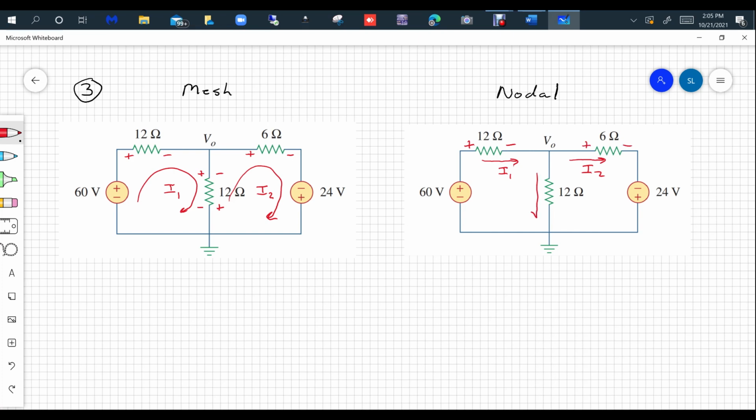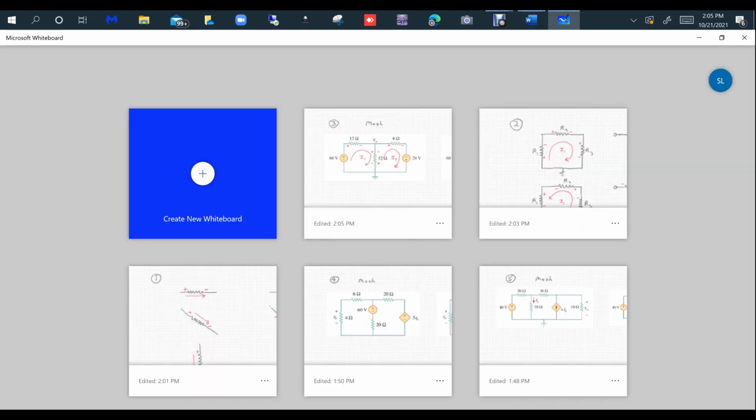And let's say usually you have that going to ground. I3. Put a plus there and put a minus there. Before you start the problem, you have to put that in. You could assign currents in different directions. It'll come out in the wash as long as you put the passive sign convention in. The importance of that, maybe I'll show you on the last slide for those of you that had nodal and mesh analysis. Let's go to the 4th.